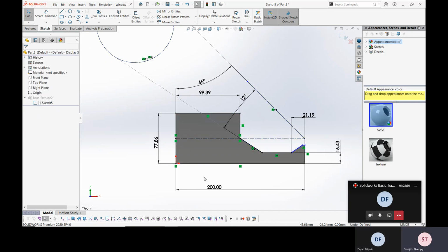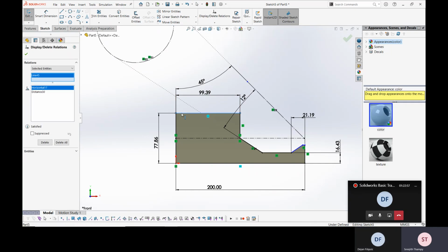I will say it once more. I want to make a change to an existing sketch with lots of relations. I'm not able to change the relations because of this particular constraint. I want to remove it. Either I can directly click on it and delete it, or I can remove constraints applied to a particular sketch or entity. I can see and delete them by selecting that one.